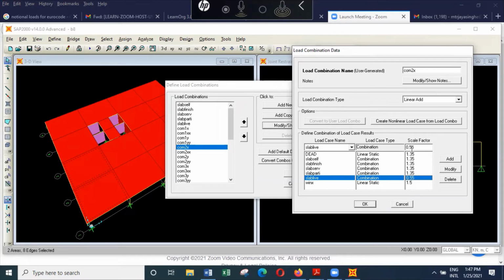That's the kind of maximum load you can get on a 1 square meter area, because you cannot pack too many people into that area. So the actual crowd loading is about 2.5 kilonewtons per meter squared. But when designing, we design for something like 5 kilonewtons per meter squared, to allow for any activity like dancing that can generate vibrations to happen on a floor that you have already designed for crowd loading.